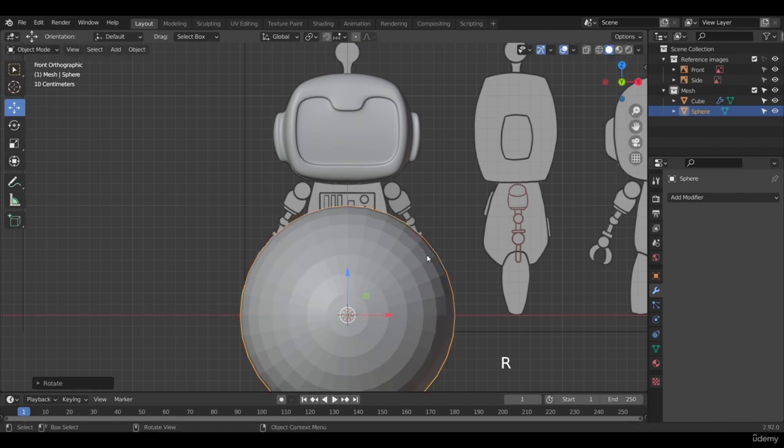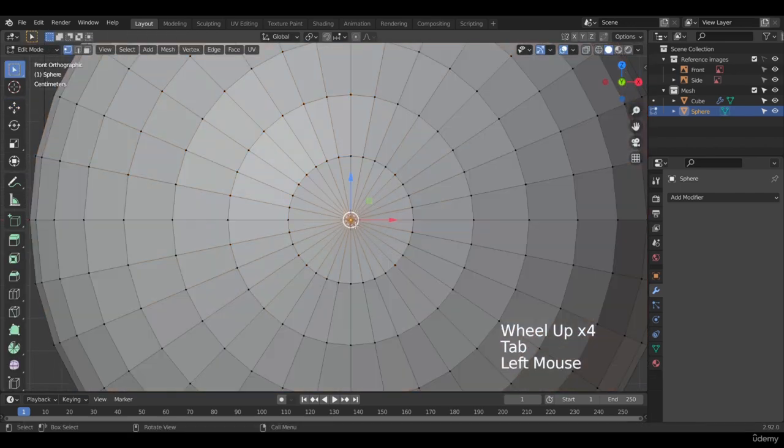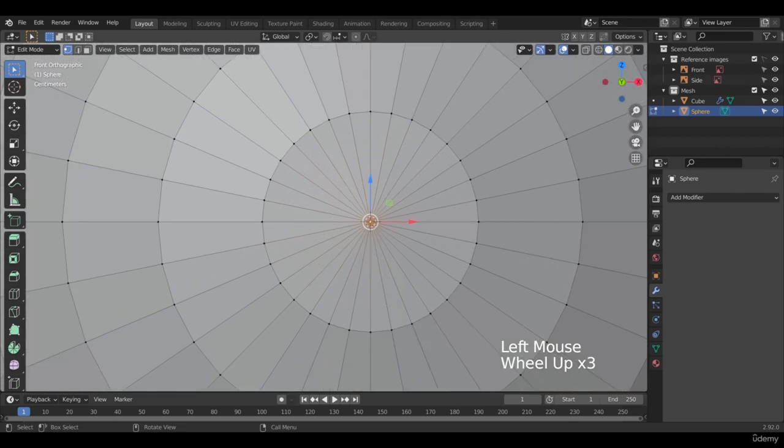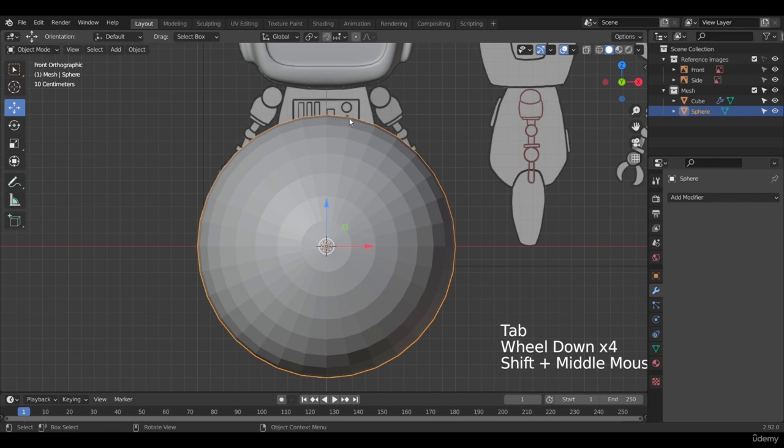If I turn this 90 degrees, you will see that there's a vertex right here that has a lot of edges attached to it, and I don't like that, just because this is like a geometry error. It's not terrible to work with a UV sphere, but I personally don't like it just because of this right here. So instead, I'm going to be using a thing called a round cube.